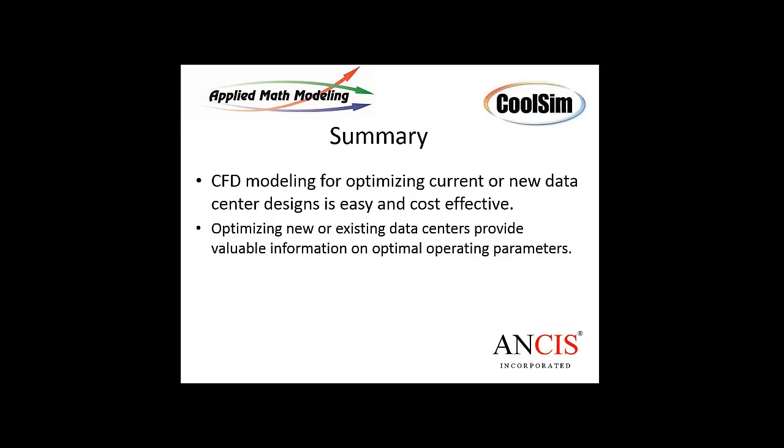Here's a question. Based on average watts per rack, how many adjustments are required to get the model correct? Not that many. Again, it's a guide. It depends if the rack is blanked or not. If the rack is blanked, so there's not a lot of leaking, and there are no holes between the servers, then average watts per rack is pretty good. The next thing I do, if I'm in a data center and I get a chance to look at it, is stare at the rack and see how many servers are in it. If I know that the watts per rack is, let's say, 10, and there are 4 servers in these slots, then I'll go in and put that detail in place.